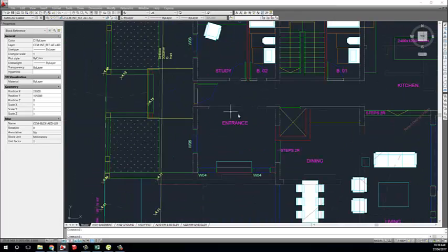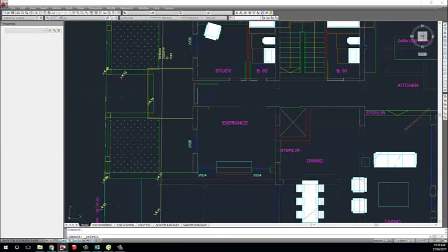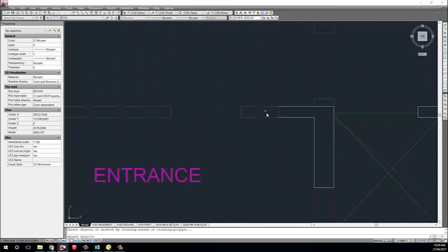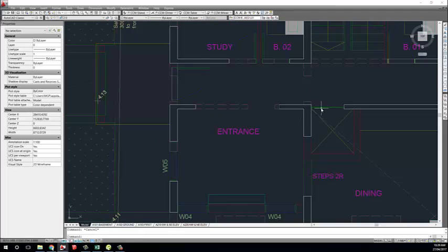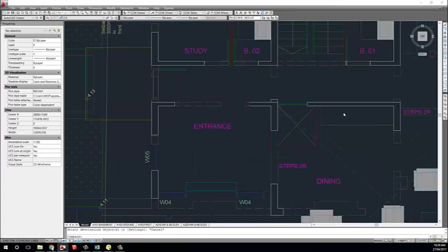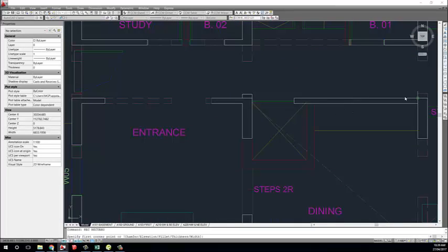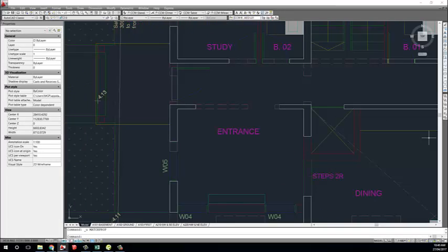So if I need to change a wall here, just go and edit block in place, and maybe we say that this is not demolition, or we transfer, or actually we're going to keep this wall instead of demolishing, but we're going to make a hole here. Okay, let's say that this is a new opening, so then this will be in the demolition, and this we have to then cut, etc., etc.